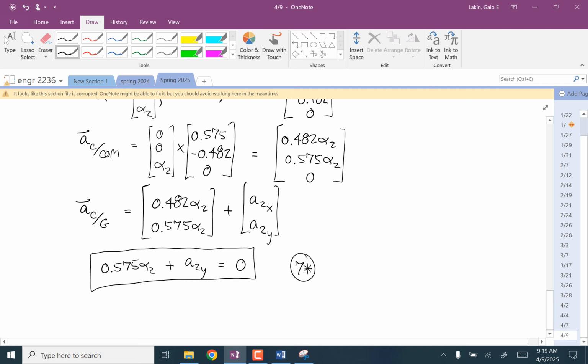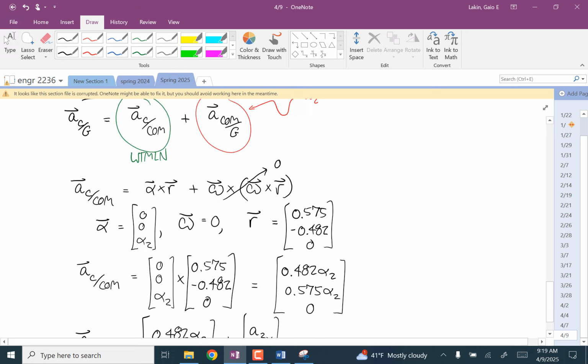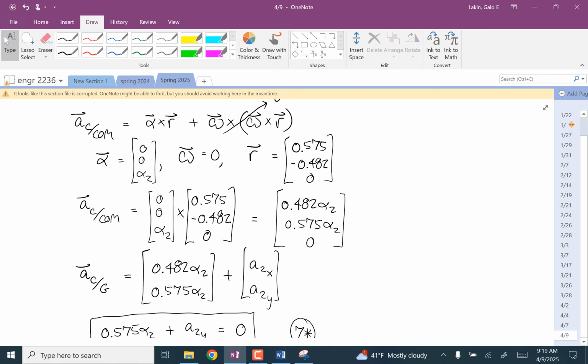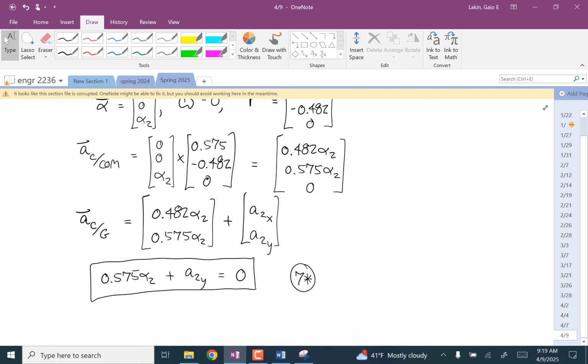Why isn't it 20 times A2X? So when you do the rigid body analysis, you're using Newton's laws. So all your equations are coming from Newton's laws. Once you get to the constraints, you're not using any kind of kinetics anymore at all. All you're doing is putting restrictions on the combinations of possible accelerations. And so all you're doing is representing accelerations and setting them equal to each other, equal to 0, that kind of stuff. And so the mass never comes into it anymore. Constraint equations will never have forces or mass in them.